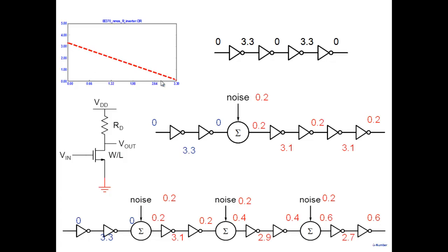So a system like this, an inverter like this, is not a very good system. Because once you inject a noise into it, the noise just stays there, because it has a gain of 1 here. So what kind of a system should you look for in an inverter? Suppose you do inject noise, what should happen to the noise?